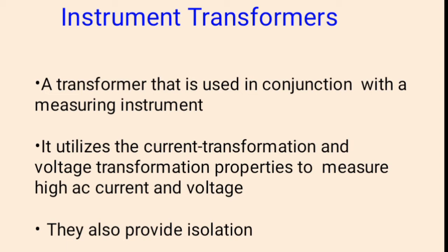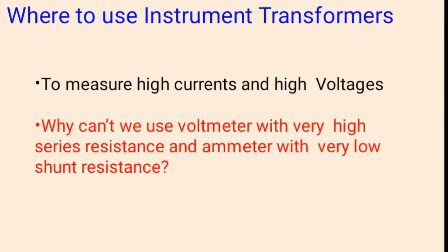The transformers are also used for isolation purpose. They are also called isolation transformers. Where to use instrument transformers? To measure high currents and high voltages, we are using instrument transformers. If you go to substations or power panels, the current transformers are used.